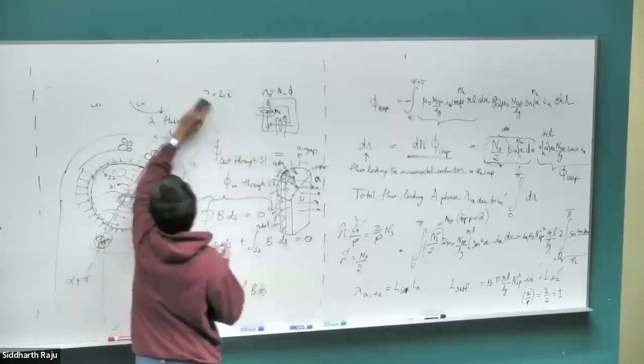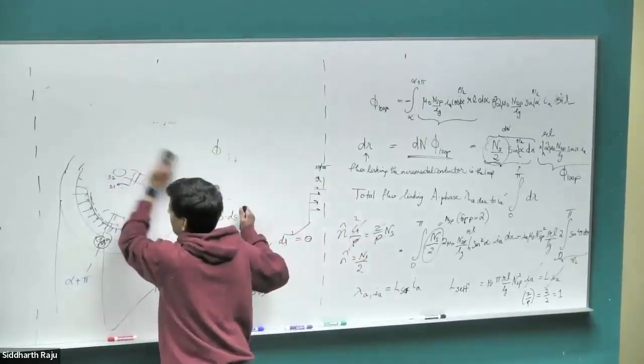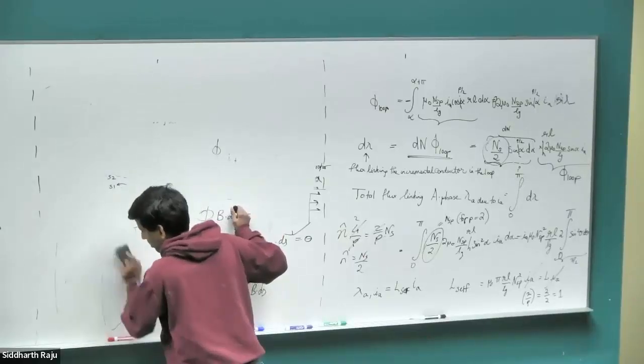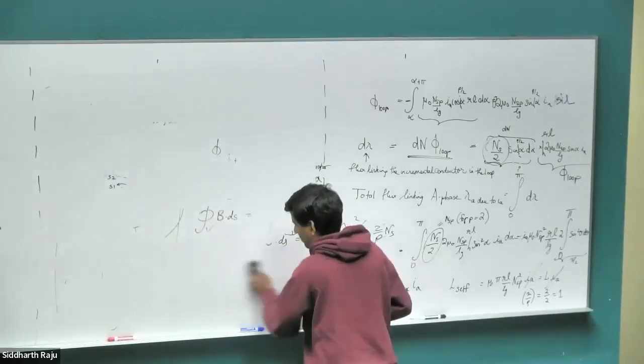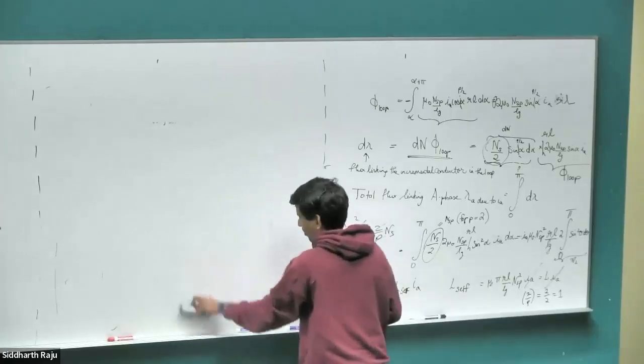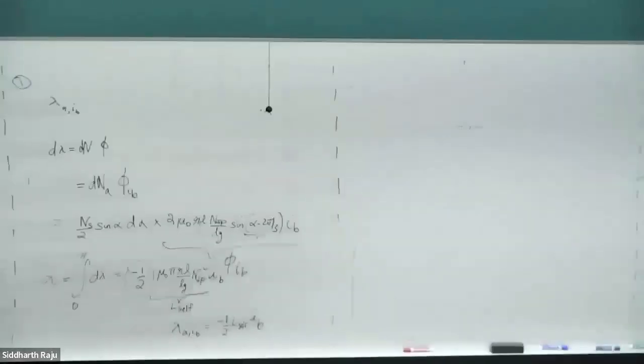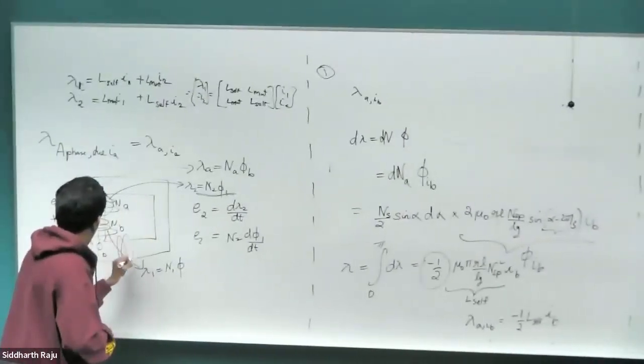Before we jump to that, let's put those terms together. So let's take it one more step. Let's calculate what the flux in the A phase coil is going to be due to the current in the C phase winding, because we have 3 phases in our motor. Right? So basically just complicating your midterm exam a little bit by putting one more coil.